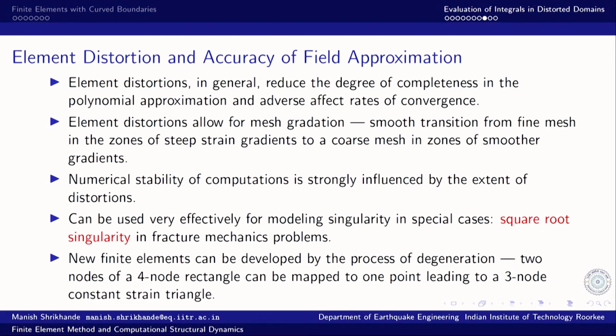By this simple mathematical parametric mapping, we can represent the infinity or singularity of the stress concentration at the crack tip, and that leads to very efficient finite element analysis of the entire problem with a very small number of elements. Further, new finite elements can be developed by the process of degeneration.